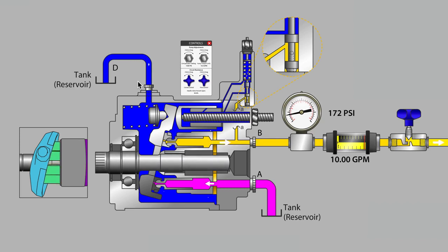And some pumps, such as flow compensating or load sensing pumps, make very small corrections to the swash plate position, or said another way, to the displacement of the pump, to compensate for minor changes in the loading of the hydraulic system. And knowing something about the case drain flow helps understand those pumps and how they function as well.